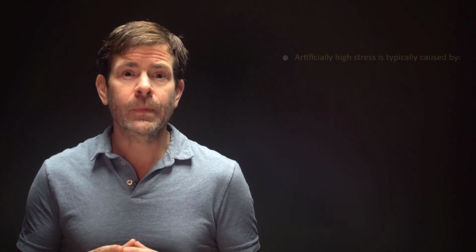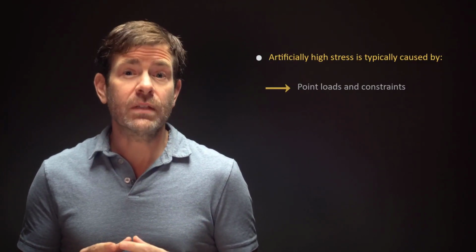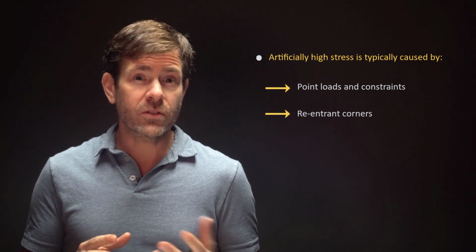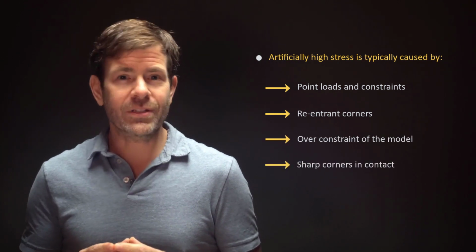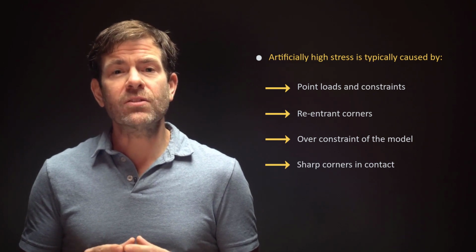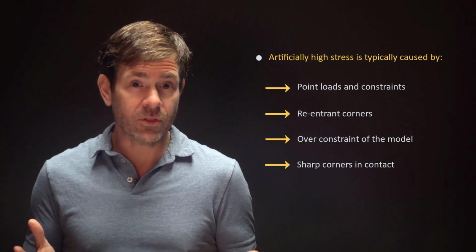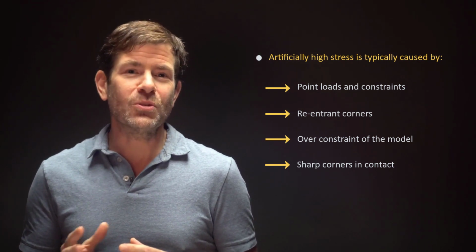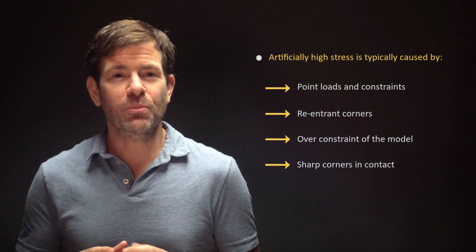This completes the workshop, so let's summarize. In this lesson, we saw when and why artificially high stresses arise in structural finite element models. We saw that the typical cases of these are from point loads, constraints, re-entrant corners, over-constraint of the model, and sharp corners in contact. While the examples we discussed may not cover every case of artificially high stresses we will ever encounter, knowing to look out for these and how to address them will better equip us to use our simulation tools and results properly.